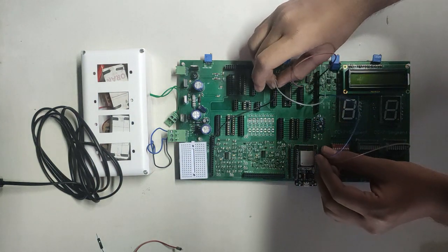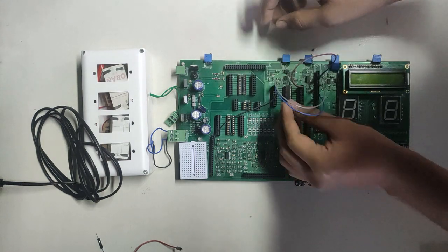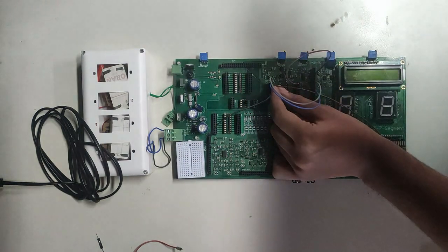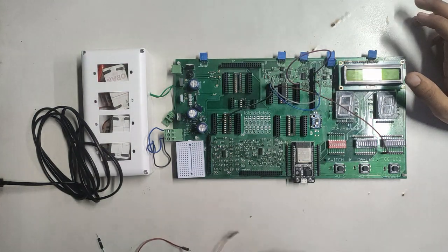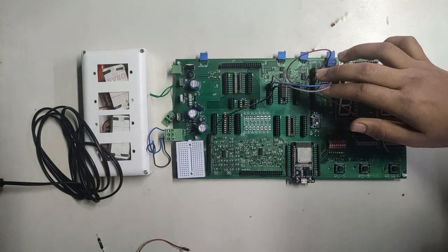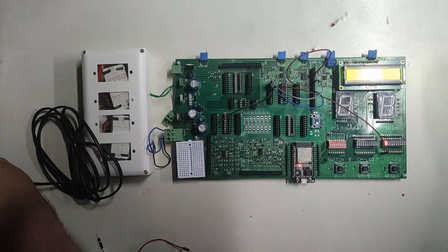So pin number 1 and pin number 2 again are the inputs of the OR gate, and pin number 3 is the output. This is how our circuit looks after making the connections. Now let us start with the last case, which is if both the inputs are plus 5 volt, or we can say logic 1, then what is the output?